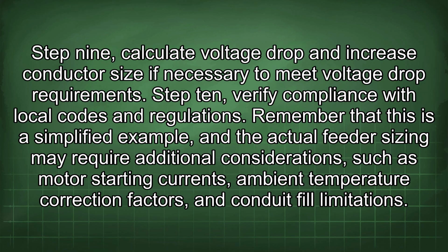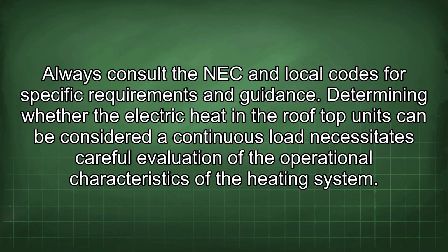Step 9. Calculate voltage drop and increase conductor size if necessary to meet voltage drop requirements. Step 10. Verify compliance with local codes and regulations. Remember that this is a simplified example, and the actual feeder sizing may require additional considerations, such as motor starting currents, ambient temperature correction factors, and conduit fill limitations. Always consult the NEC and local codes for specific requirements and guidance.